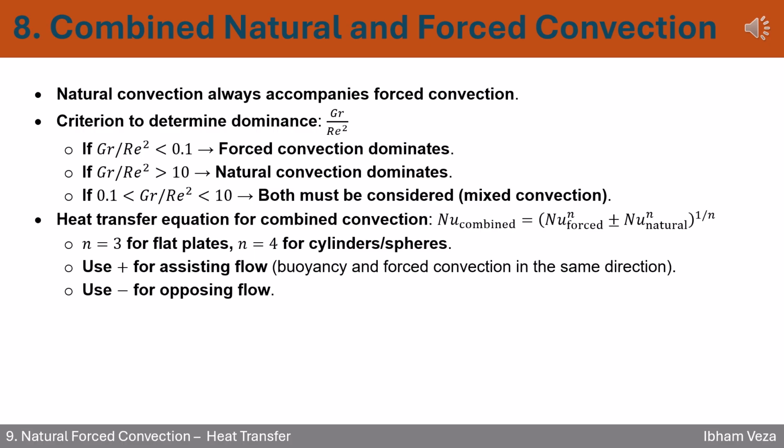You can easily quantify this with a combined Nusselt number formula. Just remember, use plus for assisting flow and minus for opposing flow. This small tweak keeps your analysis accurate and efficient.